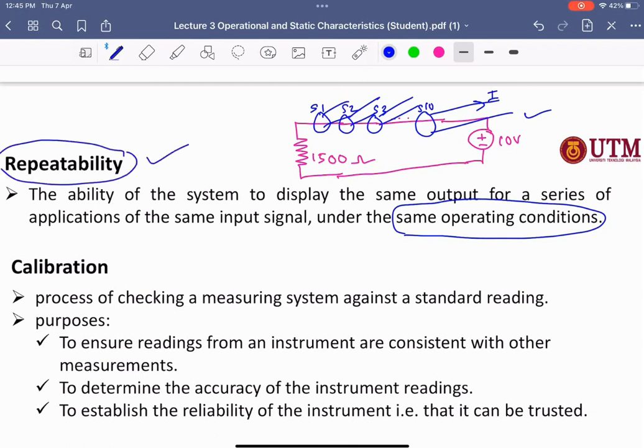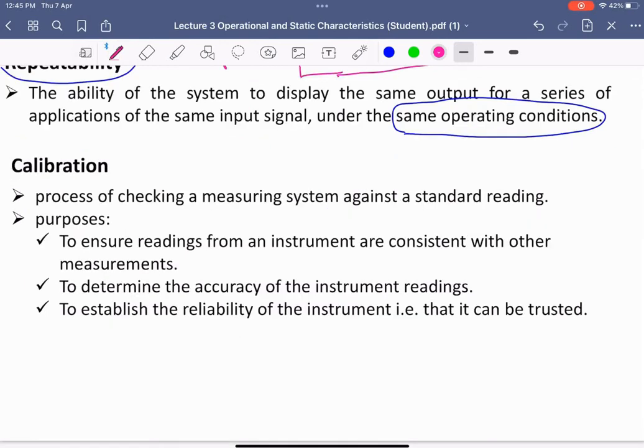Whether it is good or not depends on how you set up the experiment. And also the word calibration, very, very important when you develop the instrumentation or when you are using the instrumentation. So you need to do the calibration. Do you remember when you have a temperature gun, for example this one? How to do the calibration? That means you need a standard value.